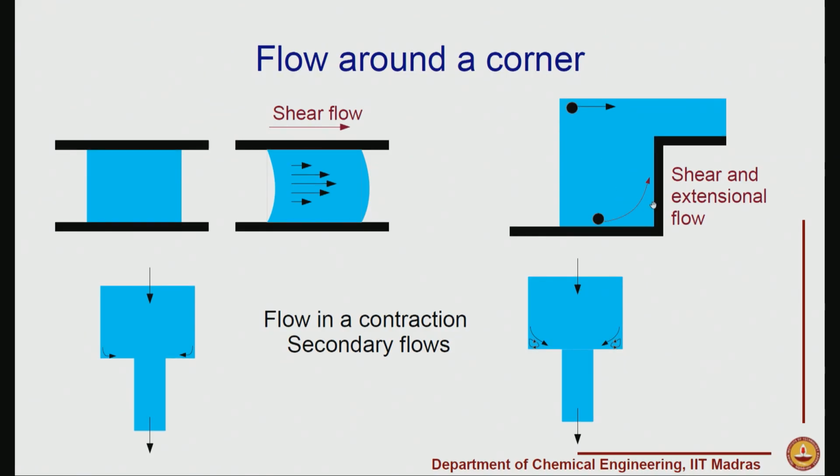So, in the kitchen itself, in a qualitative manner, we do both shear flow as well as extensional flow to examine the concentration and the molecular structure of the sugar solution. Naturally, even for complex fluids and complex materials used in several engineering applications, we tend to use both shear flow and extensional flow to characterize the material. More often than not, we may have combinations of shear and extensional flow in an application, but to characterize it in a laboratory, we either impose shear flow and try to understand the material behavior very well, or we impose an extensional flow and again try to characterize the material very well. So, let us see how this extension and shear combination may arise in a practical example.